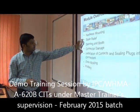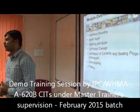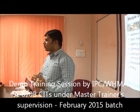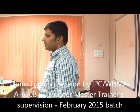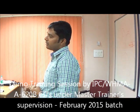So I'll be covering only these 5 sections. Before going to the connectorization, we have seen the circular connectors. For any connectorization, the process involved is wire preparation, termination, and then followed with the insertion of the contacts into the circular connector. I'll just take the example of a circular connector.